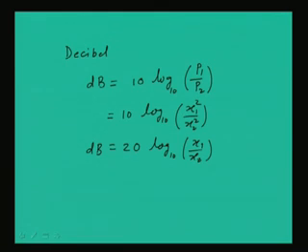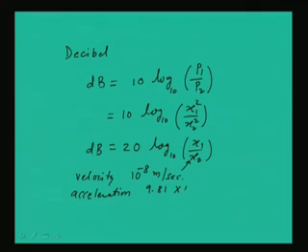You can see this is the ratio, and this x can be displacement, velocity or acceleration, and especially this denominator quantity is the reference value, and for velocity we use this reference value as 10⁻⁸ meter per second, and for acceleration, when we are measuring the acceleration, we use 9.81 × 10⁻⁶ meter per second square.